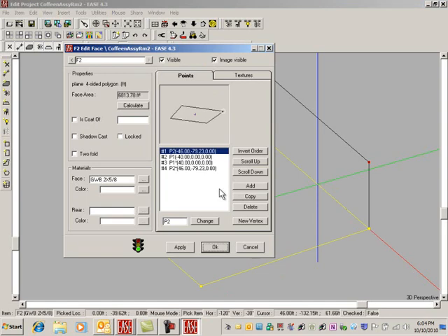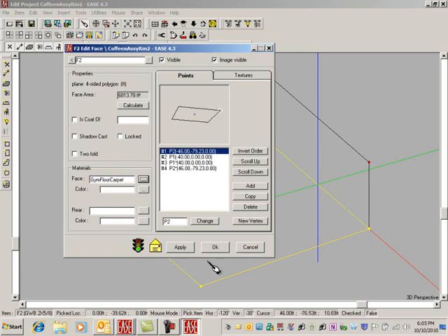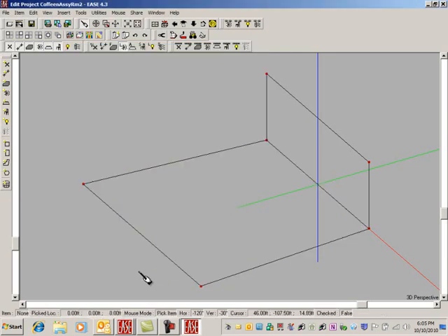Let's make a roof here. Now this is an outside. We're looking down on this roof. That's outside. So if we click here and go in a counterclockwise direction, we will have made our symmetrical roof here, like that. Create a face, yes. But now this is metal deck type 2, metal roof 2. Okay.